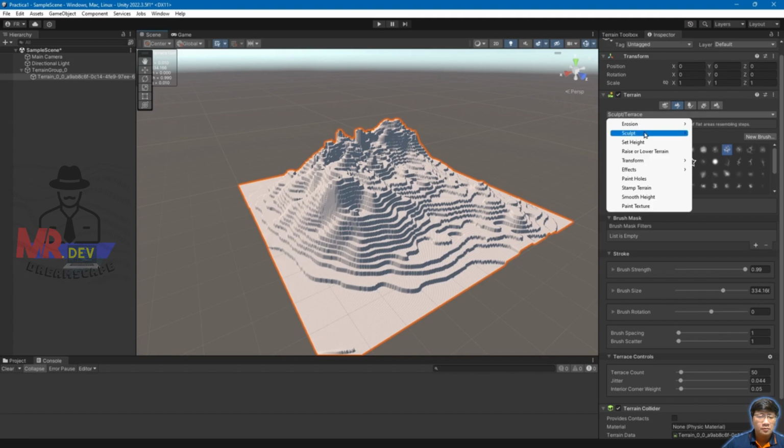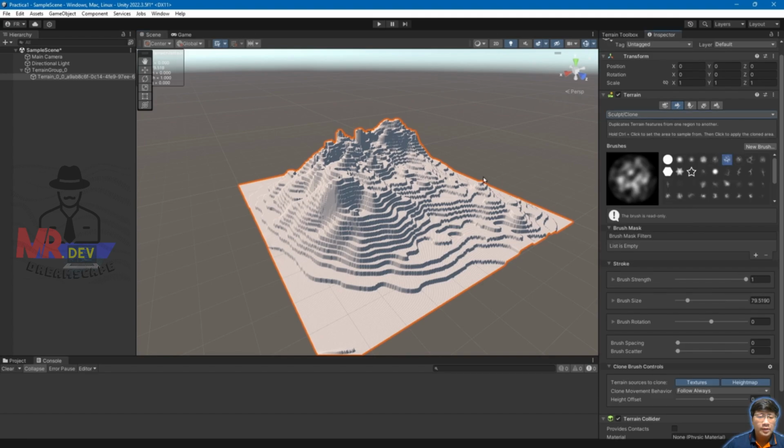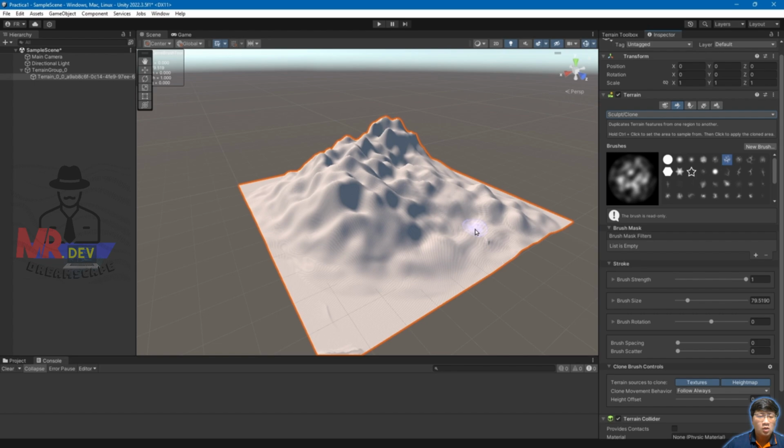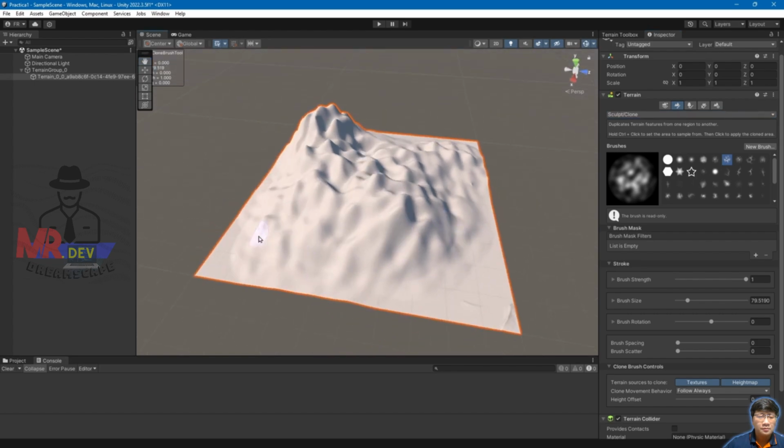Then we also have the clone. What is this cloning? I could select here with control click an area, and then clicking on another area, it starts cloning it from this side. Look at everything on the left side. There you can see where the brush is that I defined with control.